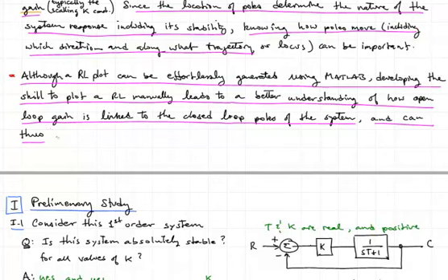Okay, so again, so far we've looked at just P, I, and D compensators or controllers, and essentially there we are placing poles and zeros on the S-plane and adding them to our open loop transfer function. And the question is, what would be helpful if I'm wanting to achieve a particular type of response? What should I add? Should I add a pole? Should I add a zero? And where should it be on the S-plane? The root locus method will give us insight.